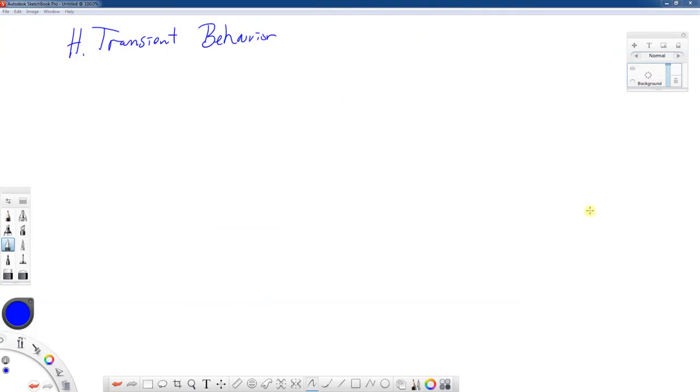Alright, so let's talk a little bit about transient behavior then. So we can cycle this in constant amplitude loading. And for purposes of our discussion right now, let's assume that we're in strain control, and we do a sine wave or sawtooth or whatever, that doesn't particularly matter for us at this point. But we will develop our hysteresis loops. We can increase the amplitude. We can get larger hysteresis loops as we have more plasticity and so forth. And we can construct our monotonic and cyclic stress strain curve. So let's see what a couple different behaviors might look like.